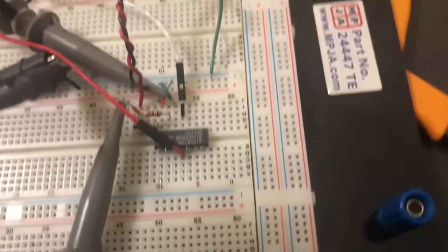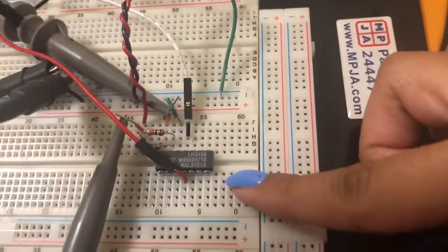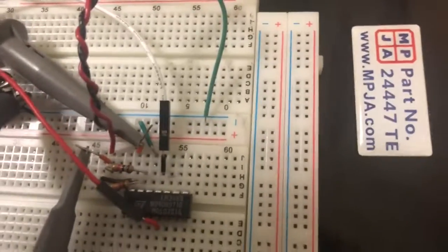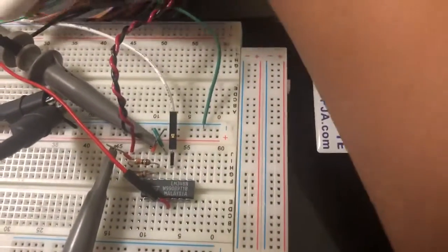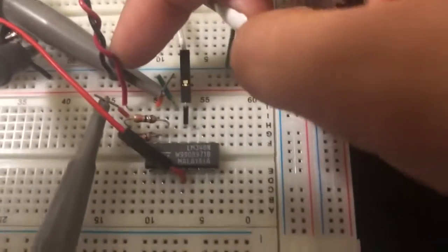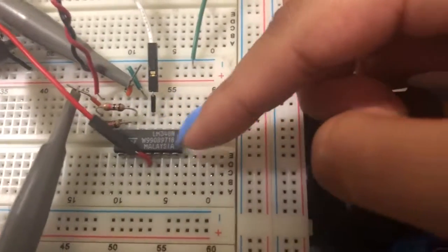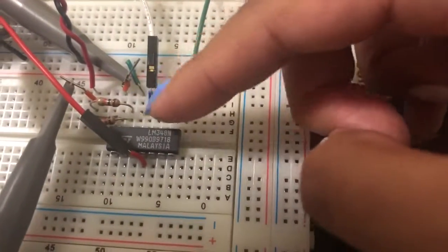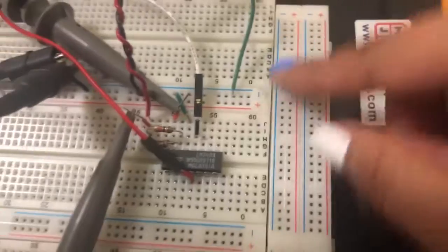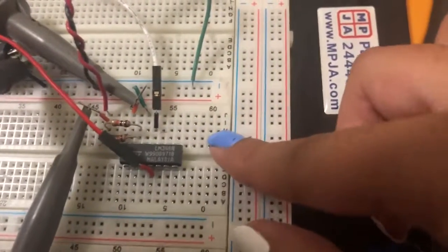So here we have our op-amp chip, powered by a -5 and +5 volt source. And here's the input square signal to the amplifier. We also have R2 and R1 connected here at a ratio of 12:1, so that our gain is 12. However, we have a power supply going from -5 to 5.